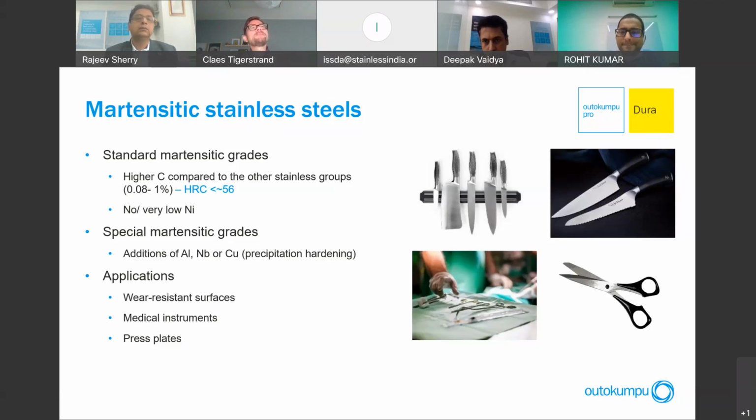Yeah, molybdenum could be very much negative if you are in an environment that is more alkaline and hot nitric acids, for instance, a very oxidizing environment that you can also encounter in, for instance, the pulp and paper industry. There the molybdenum will have a negative effect.